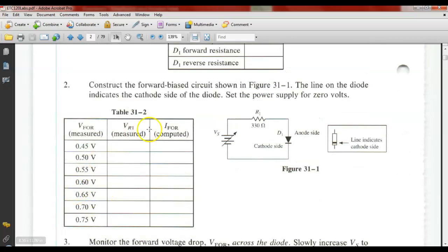It's going to be variable. This is the symbol of a DC source. Originally, this was the symbol for a battery because that was the first DC source people figured out how to make. This is a symbol now of a DC voltage source. It could be a battery, it could be a cell, it could be your rectifier out there on your car. If it's got an arrow through it, it means it's going to be variable. So you can't use any of the fixed power supplies on there.